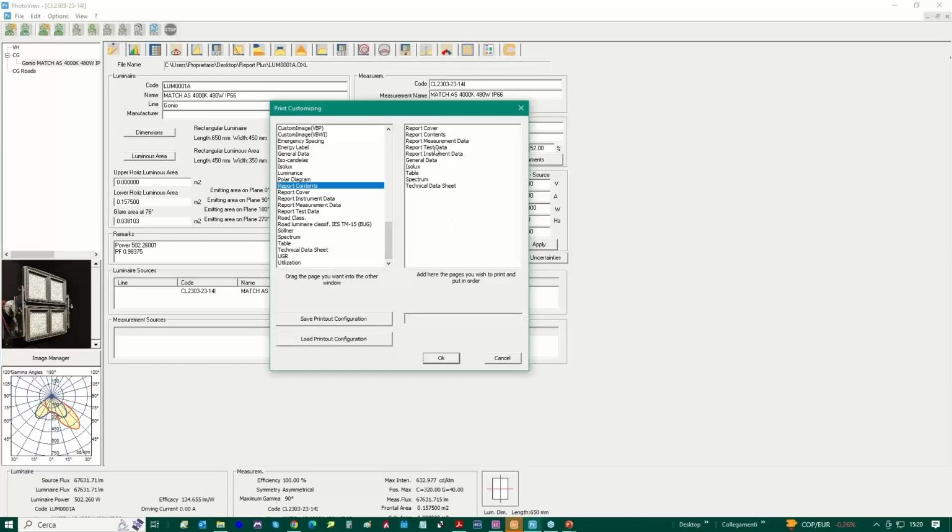about our report. So it is also possible to save the printout. For example, we do not use the same printouts and graphics for different luminaires. So a road luminaire has a set of printouts of its own, like a floodlight, like an interior luminaire. They have different approaches because they are about different areas. And so you may save different printout templates, so that you don't have to define, any time you need to print, the new set of printouts you want to use.